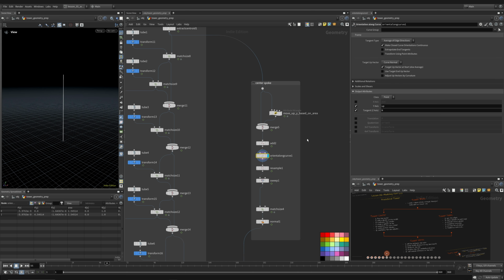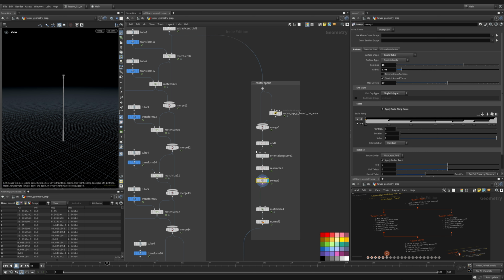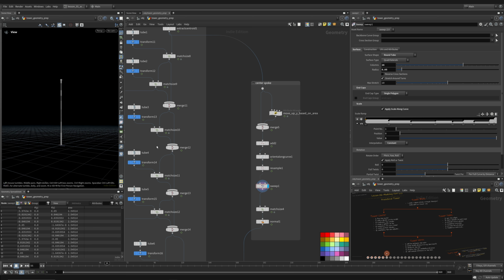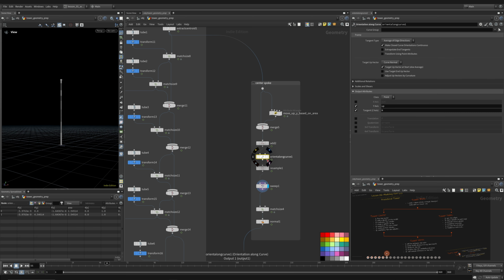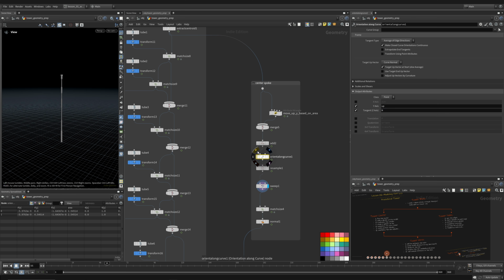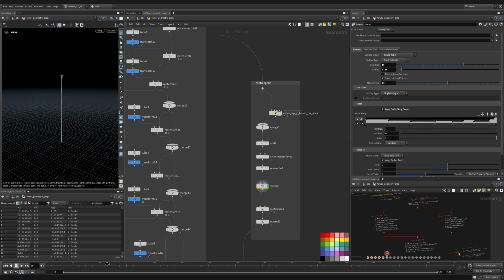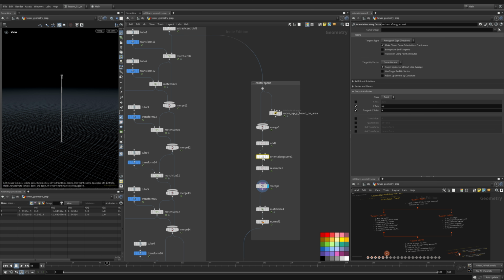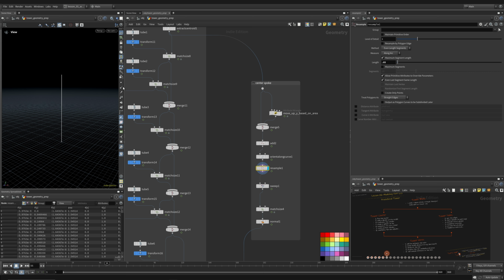We orient along the curve, which is used to sweep the geometry. We don't technically need this in this case, but when you're sweeping curved geometry, or if it was a distorted line, you would in general want to have this attribute, which creates an up attribute and then an N, a tangent normal attribute, which is helpful for working with curves. So if you are sweeping something that's displaced, you might get a weird result if you do not have these attributes.